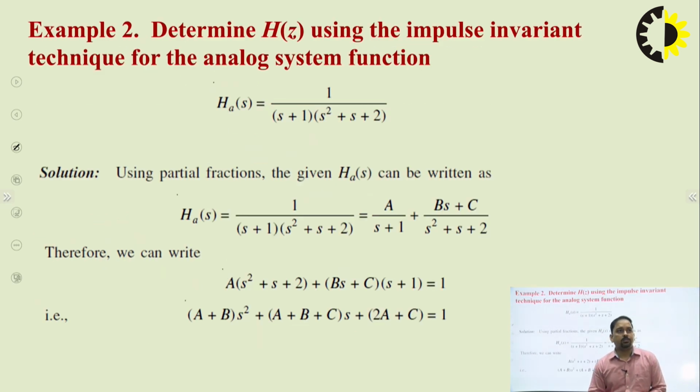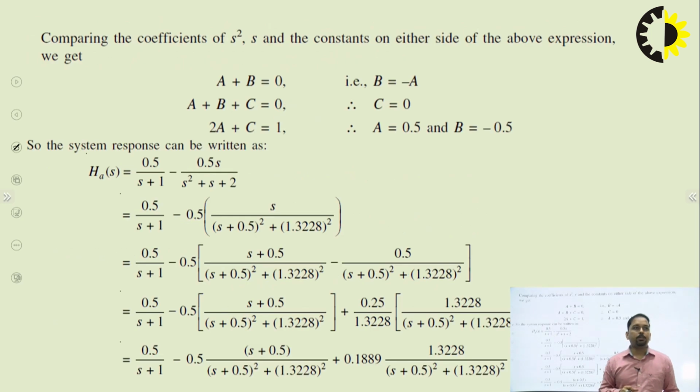Similarly, we have a different question. This is quite important, because this transfer function Ha(s) is not available in a standard form. So we need to convert it into a standard form by taking the partial fraction. Let's say this is equation number 1. The basic method again remains the same. Either we can calculate the corresponding impulse response, or we can convert these H1 or H2 into a standard form, like what we have converted here.